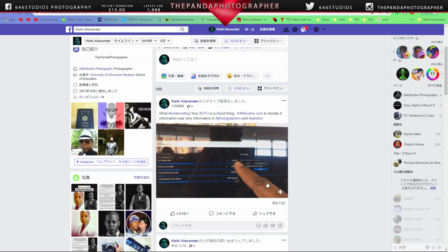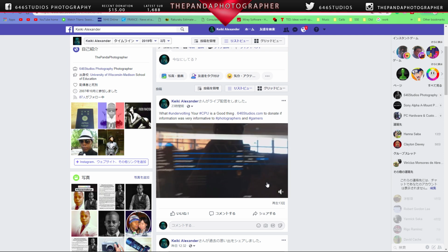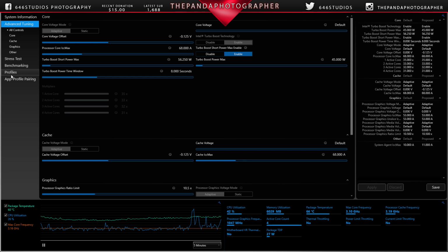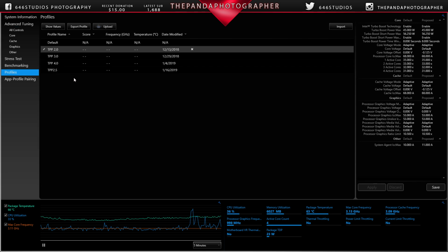So I do have a BIOS profile setting. Okay, so let's go back into this. I do have a profile of different undervolt settings. I noticed with my particular 6700HQ, now not all CPUs are made equally the same. Yours may vary. You may not want to achieve 140 millivolts of undervolting. Yours may max out at 130.